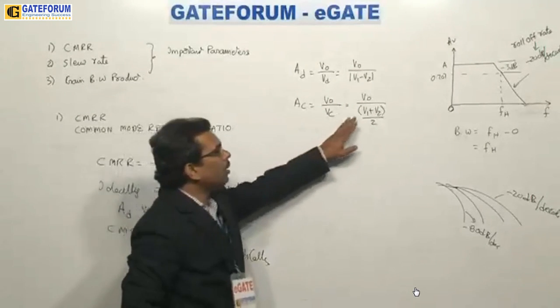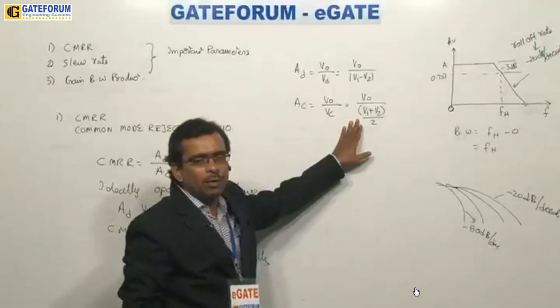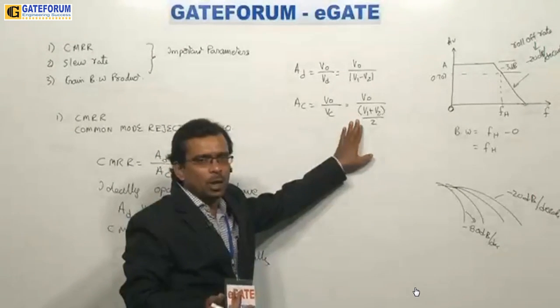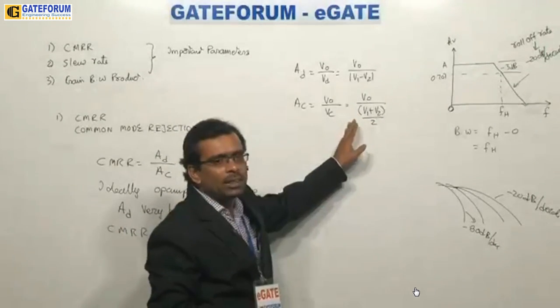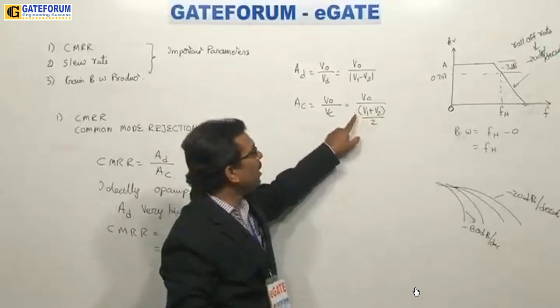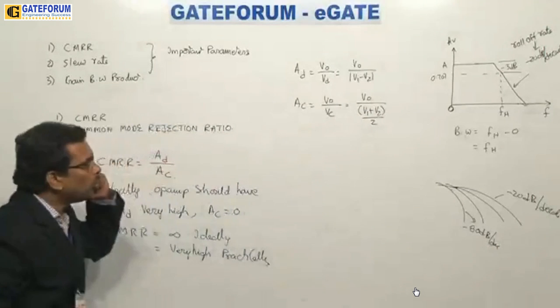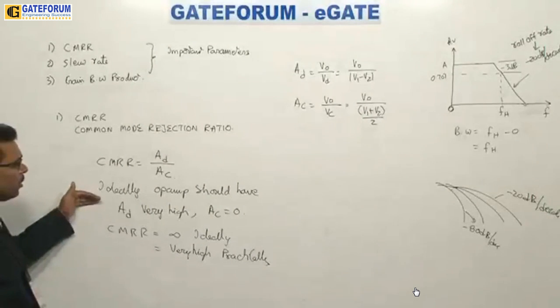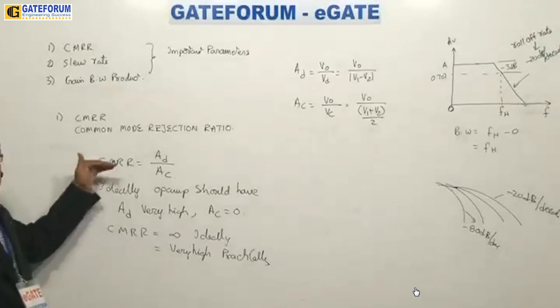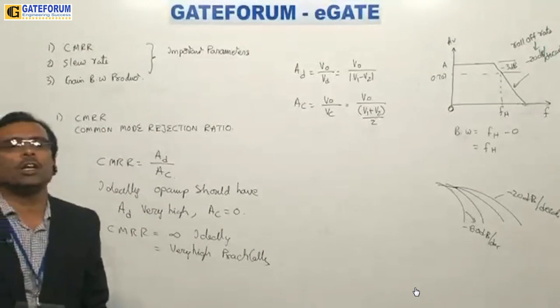So this is an unwanted signal which will enter. We don't know how much exactly enters, because it's a noise, a random signal. So we take the average of the two inputs entered as a noise signal into the op-amp and write this as (V1 plus V2) by 2. This is what we call the common mode signal, and this we consider the difference mode signal.